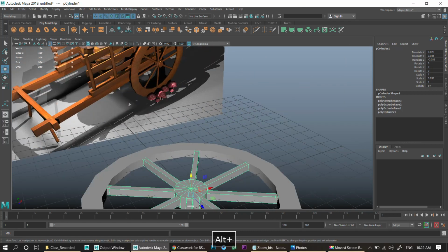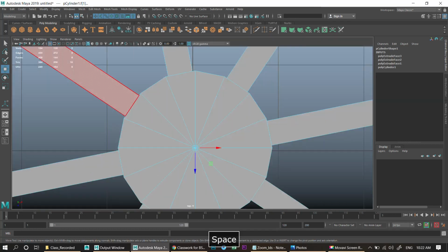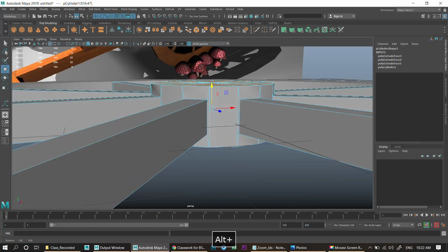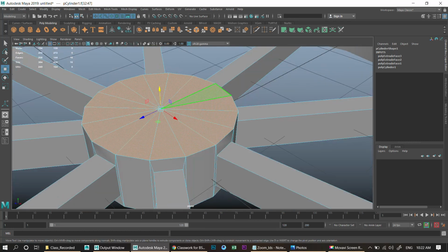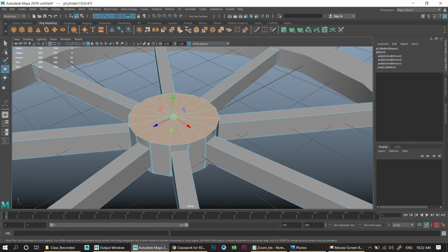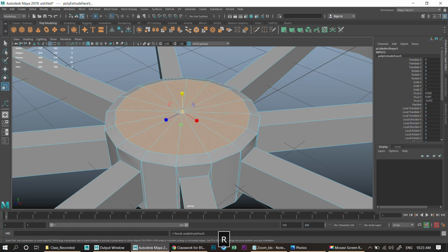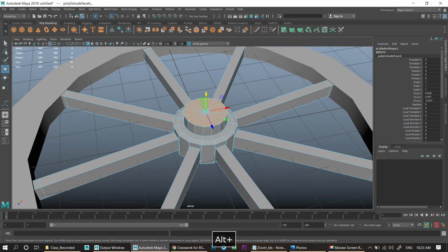Have a look at this image. We have one more extruded portion from here. I'll select this top portion by drag select, and obviously the bottom also got selected. Holding Control, deselect them. Make sure nothing extra is selected, and extrude again, scale down and move a bit, extrude again, scale down, and extrude again. I'm pressing G to repeat the last used command.